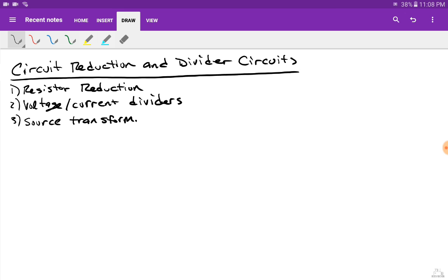You should know what a short circuit is, an open circuit is, and you should also know what a resistor is and its fundamental current to voltage characteristic. Basically, V equals IR. We call that Ohm's law. All right. So now that you know all of that, it's time to learn some more stuff. But at this point, you haven't really had to do much more than KVL, KCL, and then combine the two equations with Ohm's law, as you need to do them.